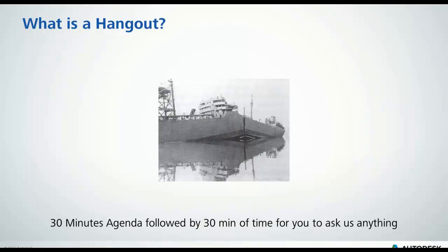So anyways, we're going to talk about different weld analysis. I have a few demos to go through. The three methods that I'll be covering are modeling the welds as a solid, using the welded contact parameter, and in some situations you may need to generate contact elements to close gaps. So we'll be looking at that method for simulating welds. All of them have their advantages and disadvantages, and they come with assumptions that we will discuss along the way.